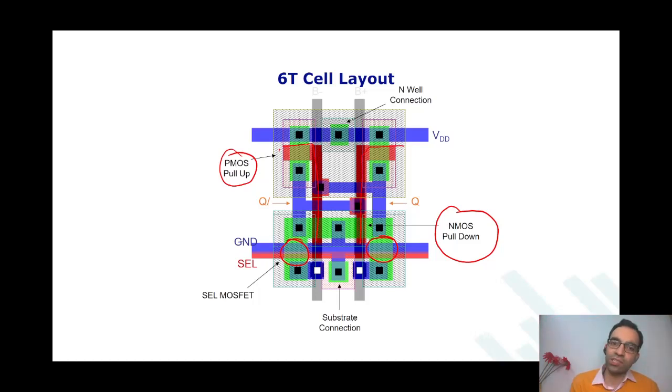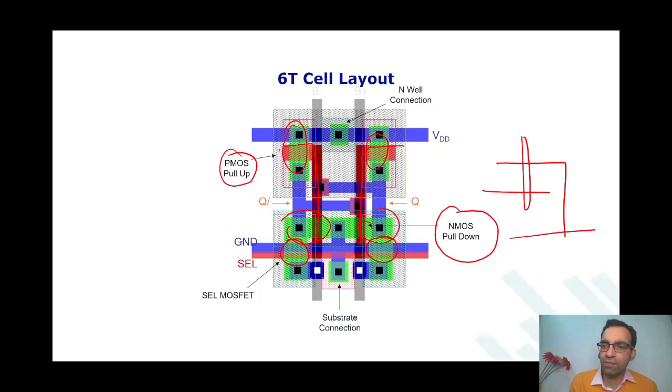The direction of PMOS device and NMOS devices is different. There is a bend in the NMOS device itself. There are pull downs which are vertical, like this, and pass gate which is like this. Anyways, in advanced technologies, you want to keep things as simple as possible, not have any bends, nothing. So there are so many bends.